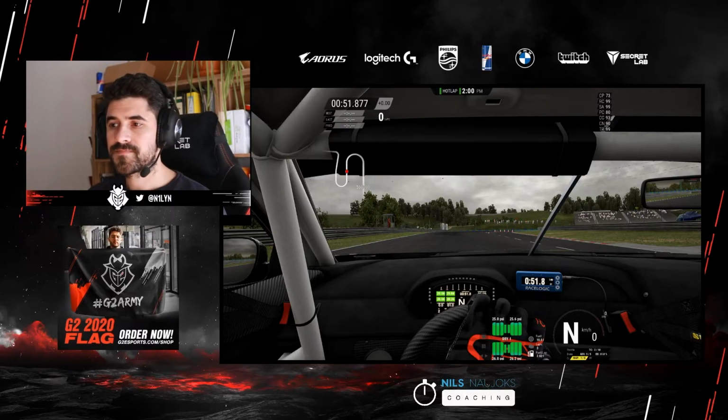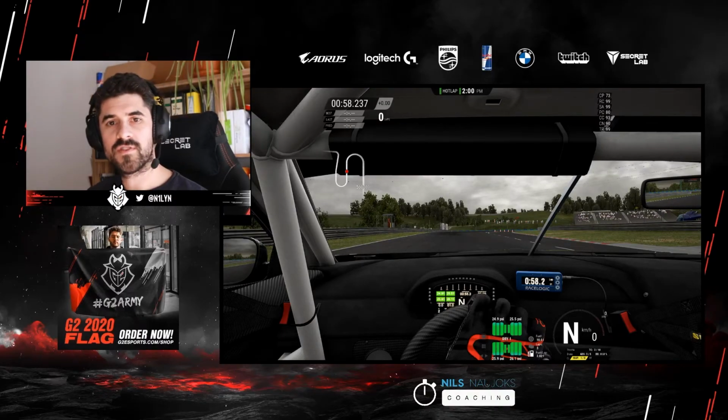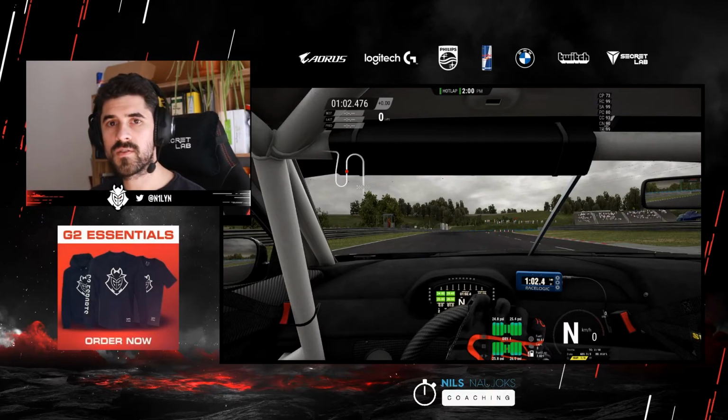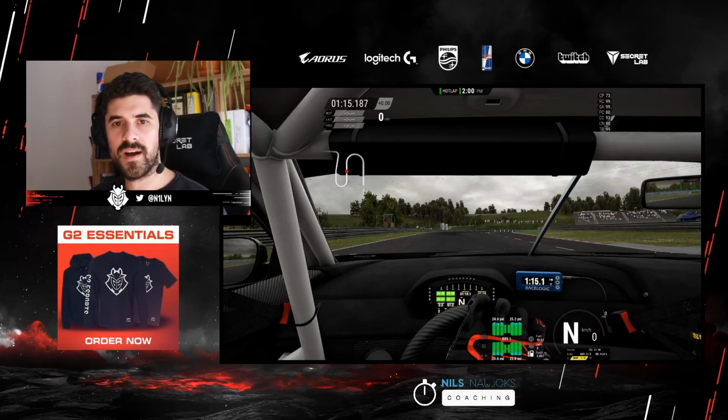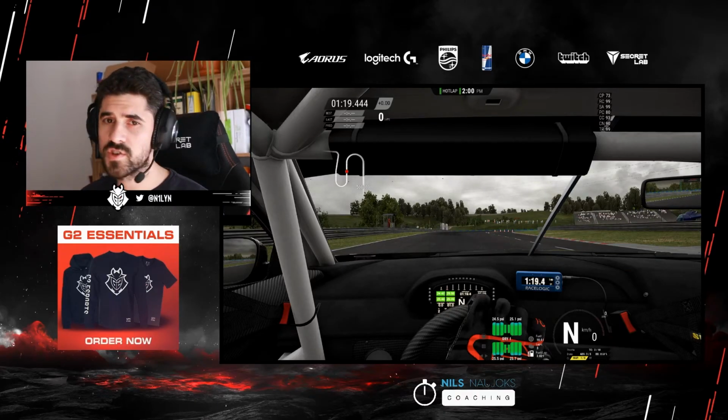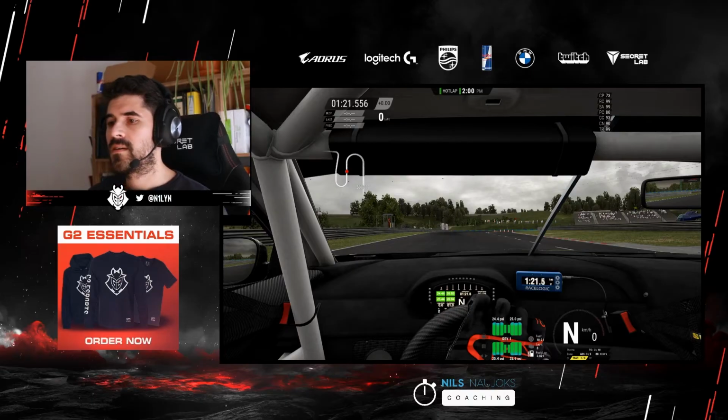Which means your pressure in the pits always has to be fairly below what you will eventually want to have on track. And your target for the dry tires is somewhere between 27.5 to 28.0 psi. This is the range for almost all cars. There might be slight variation of 0.1 or 0.2 psi, but more or less you'd be perfectly fine on all cars if you go for 27.8 or something. This should be well in the window.